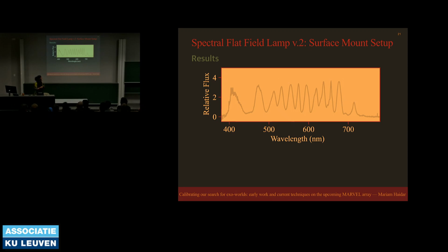And that's because, when the light is going from the LED across through the optical components and finally into the fiber, when it's reaching a limited output size, the light from the two sides of the wavelength spectrum is being cut off. So it's not that this LED, for example, did not stretch to the left and the right further. It's that the light from these ends was cut off, and so you're missing that information.